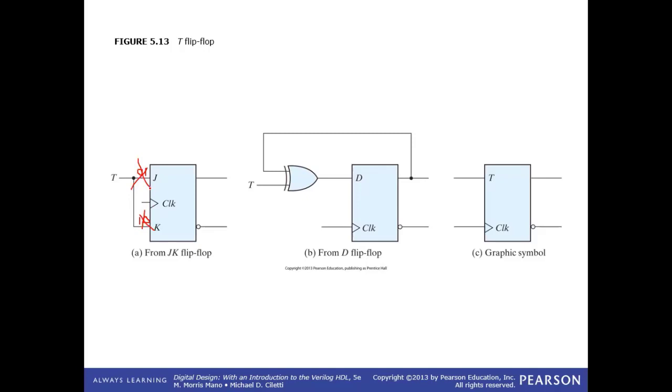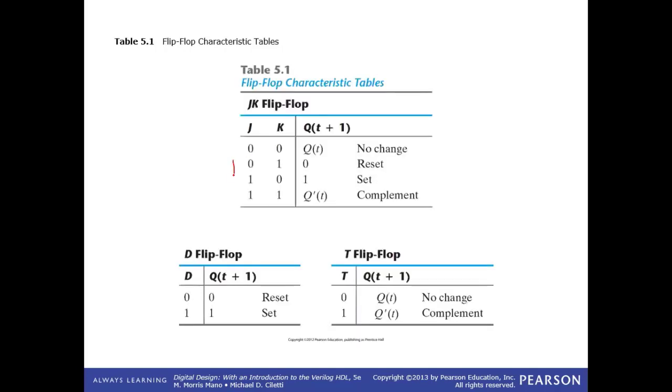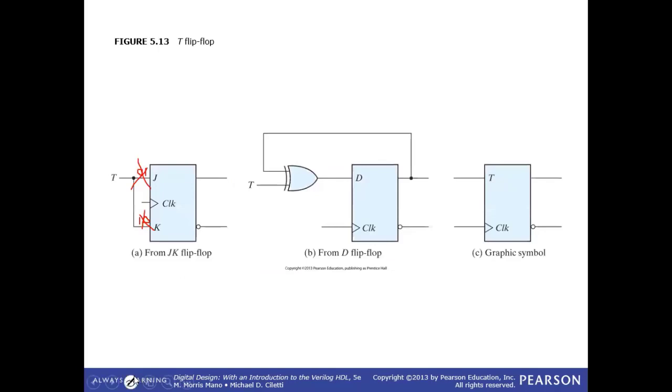So this means you can never have the set and the reset capability. You cannot set or reset the JK flip-flop. Sir, either there will be no change or the output will complement. Very good. So we have only one of two options available: either T is 0, and the output Q and Q bar will retain themselves and not change, or if the toggle input is 1, Q would become equal to Q bar, and Q bar would become equal to Q.